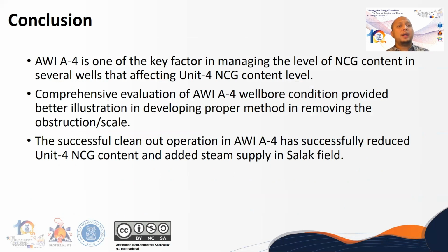As the conclusion, Awi-4 is one of the key factors in managing the level of NCG content in several wells that affecting unit 4 NCG content level. Comprehensive evaluation of Awi-4 wellbore condition provided a better illustration in developing proper method in removing the obstruction or scale. And the successful clean-out operation in Awi-4 has successfully reduced the NCG content in unit 4 and also added steam supply in Salak field.